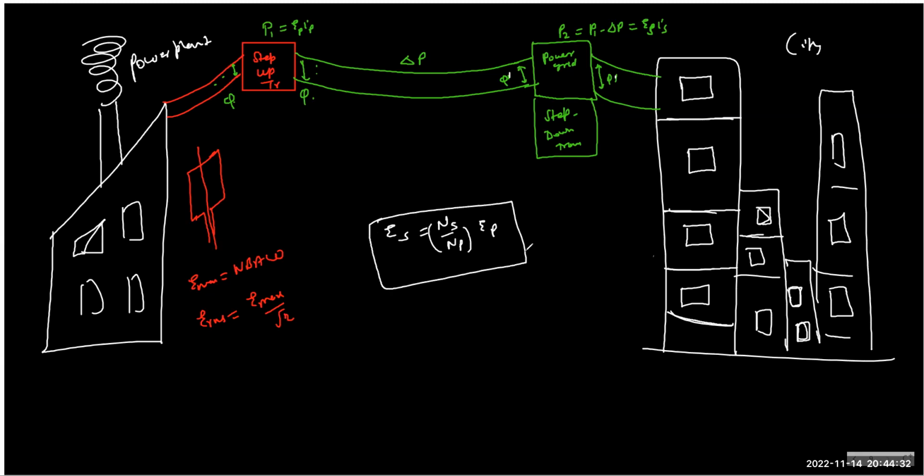And we are assuming there is no flux leakage. If there is no flux leakage, this is the equation you can always go with without any hesitation. But the current relation depends on power, so you have to think of power first. This is the relation I have written here. If you have loss from here to here, the current here will change accordingly. So keep these things in mind, and hopefully you will not face any difficulty in solving questions of transformer. Okay. So with this, we complete our alternating current.